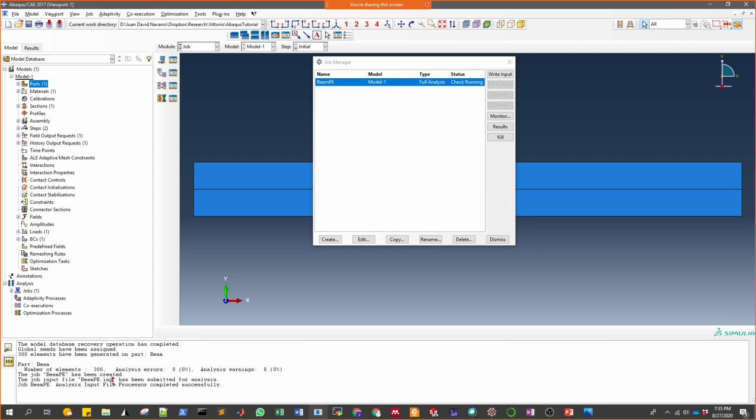The finite element method divides in three stages: pre-processing, processing, and post-processing. What we just did is the pre-processing, and the software is just validating that file. The processing is what the computer is going to do, all these calculations on the system of equations, and then the post-processing is getting those results to create plots and diagrams that will allow you to have conclusions as an engineer. Okay, it says completed successfully.